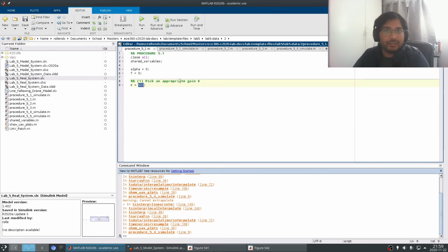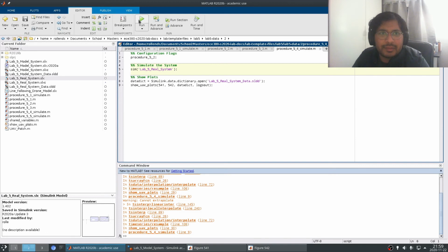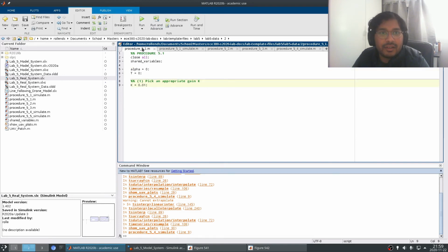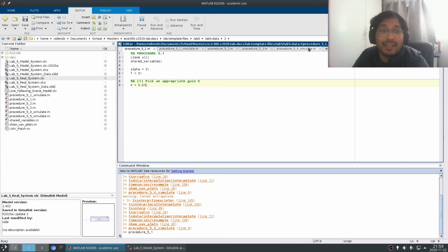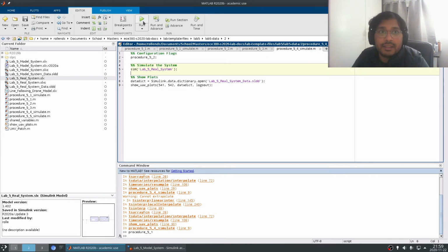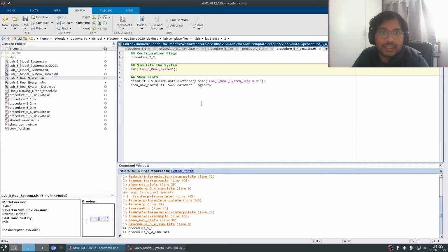If I were to maybe change some gains here, so if I made the gain really small, which you can't do actually for this lab because you'll need to meet a specification, the closed loop system will probably be stable, but it's probably not what you want. And you're going to use the lead lag compensator design to actually both achieve the steady state spec as well as getting stability. So let's run this. I suspect this will be stable, although it will probably not be an ideal convergence.